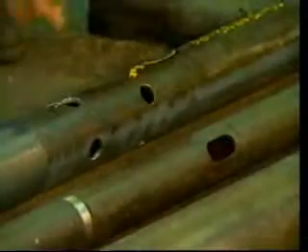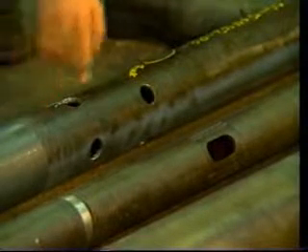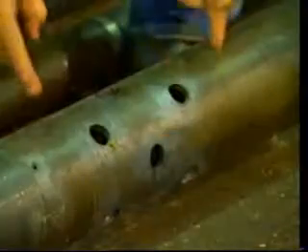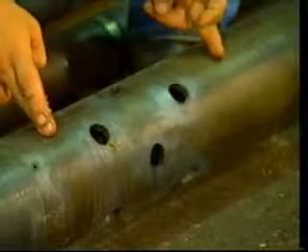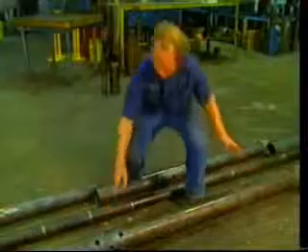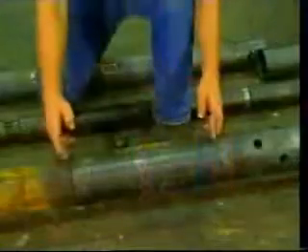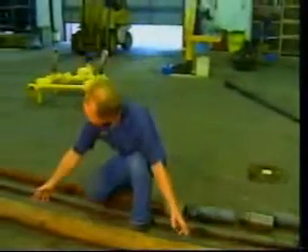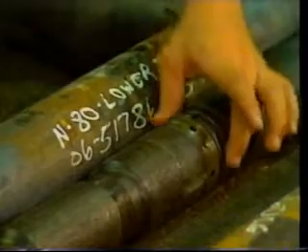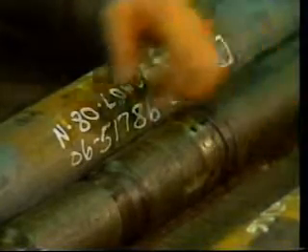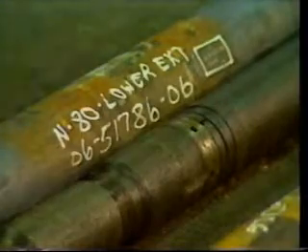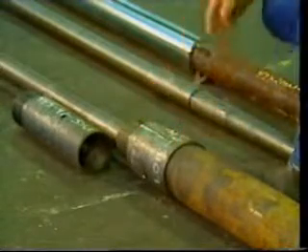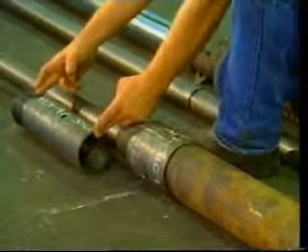As shown in the disassembled tool string, the perforated extension contains the crossover tool assembly and its gravel pack port, through which gravel is pumped into the extension and out the perforations. Below the perforated extension is the seal bore sub, and attached to it is the lower extension. The indicating ring on the setting tool crossover assembly, just above the wash pipe, forms a seal against the seal bore sub during gravel packing.